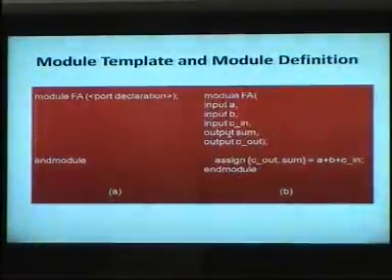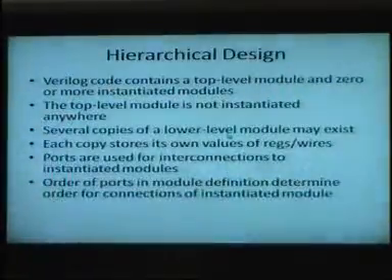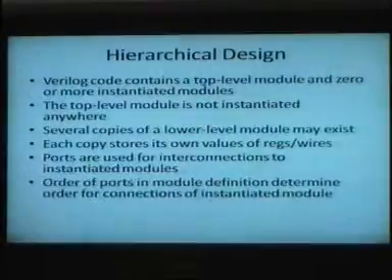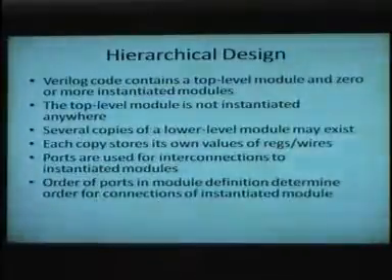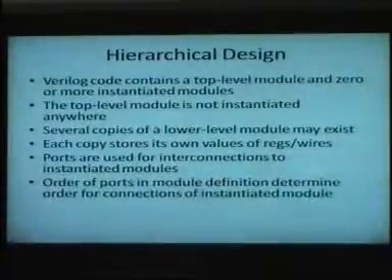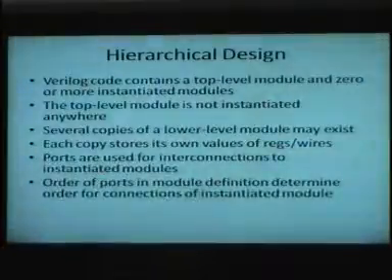So module definition is like this: you have inputs and outputs, and usually in Verilog it's again important to structure your design, and we say that we use hierarchical design concepts in Verilog, because it's not software, it is hardware. Hardware is a physical thing which you are designing. So it is going to be something physical. And we always think in terms of physical modules, so we design it in a hierarchical manner.